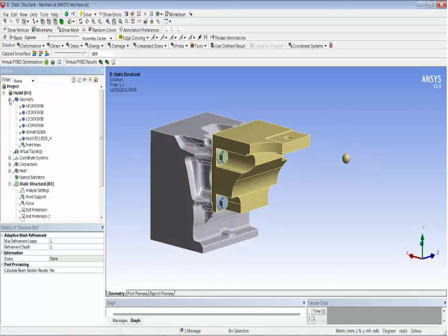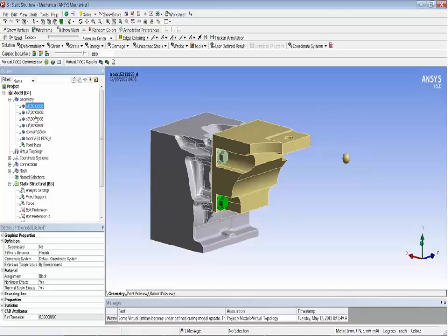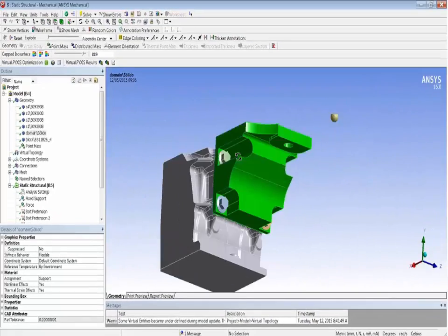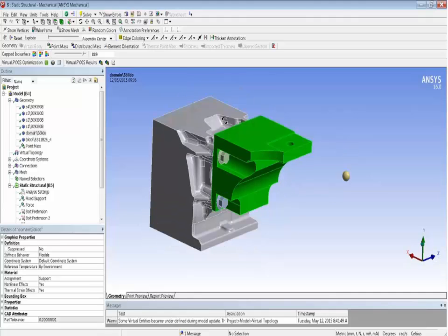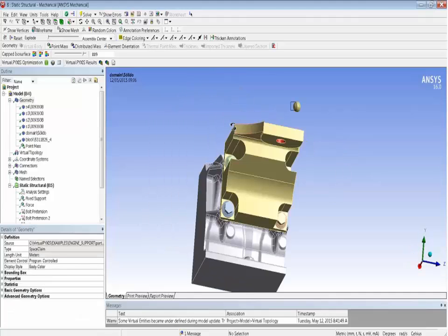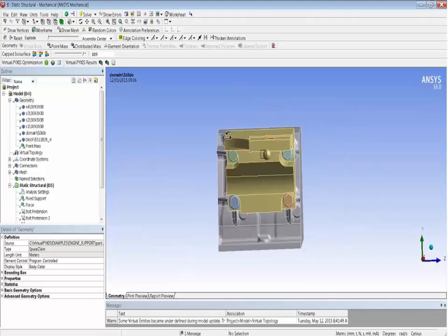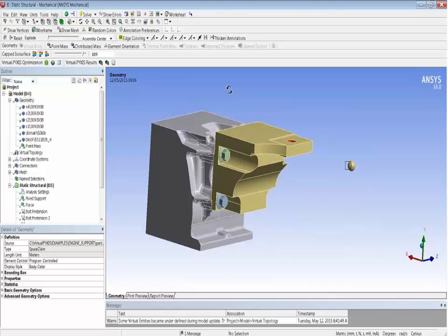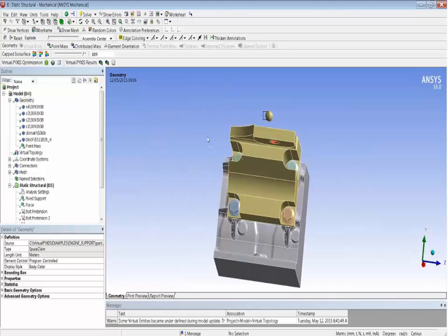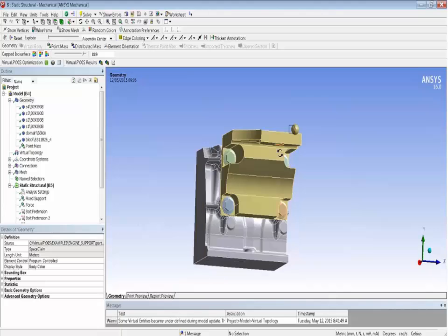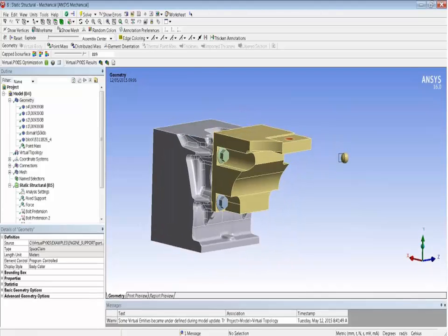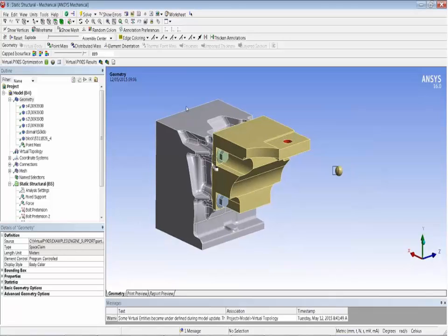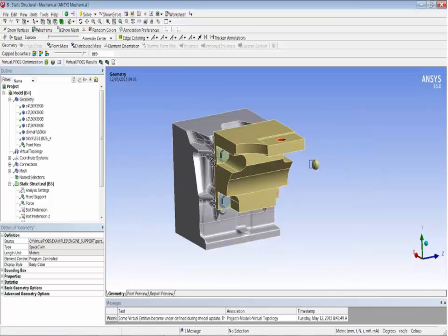The support itself is this part, in green now, and as in the chair example, we have an extended design to give the software the opportunity to get the best design for the optimization. We also have some screws here, represented later by bolt loads, which also give some stress around this region.